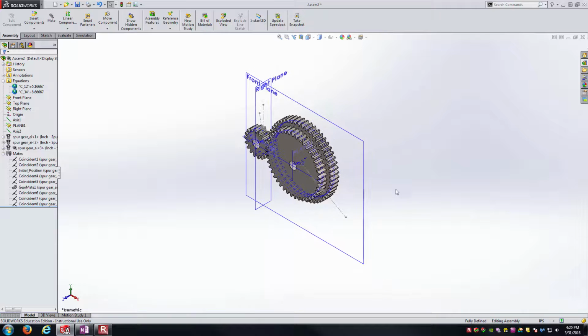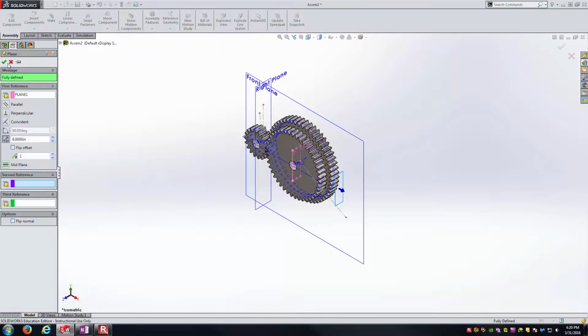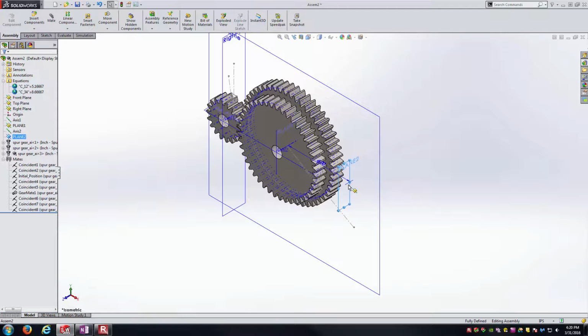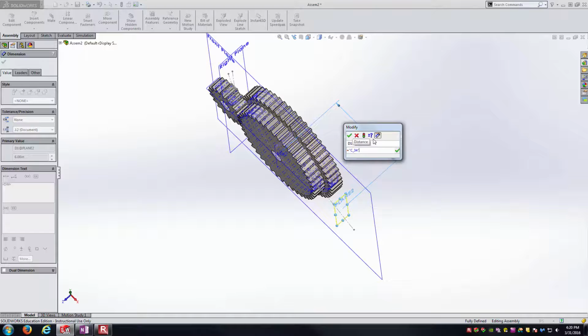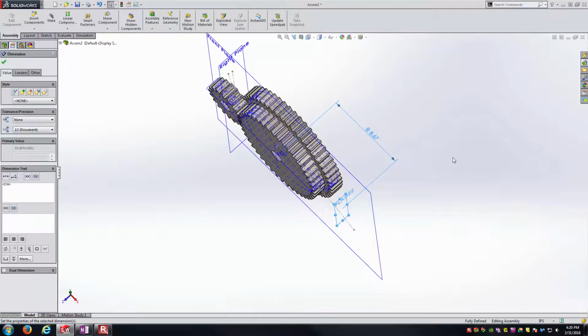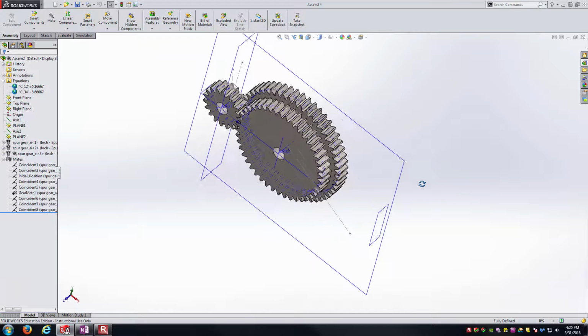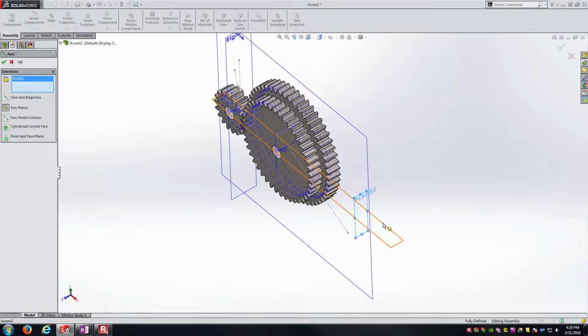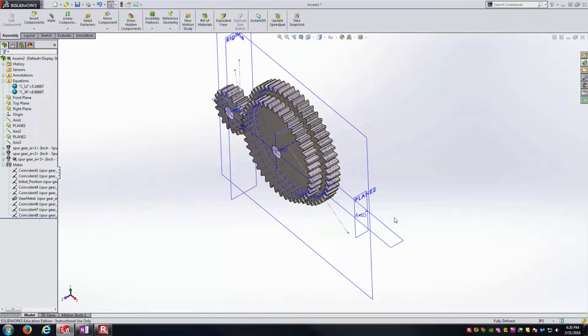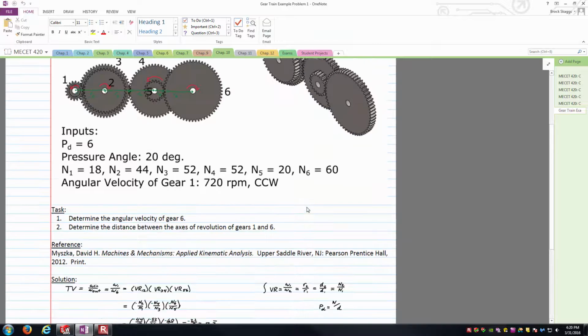Okay. Same method here, except we're going to use this plane here, plane 1, as our reference. So we'll go reference geometry here. We'll just accept the default 6. Then I'll come back in here and adjust. Now this is going to be equal to C34. Rebuild, and you can see the plane jump out there. And now a matter of creating the axis again. We'll go from reference geometry axis, plane 2, in the top plane. There's axis 3.